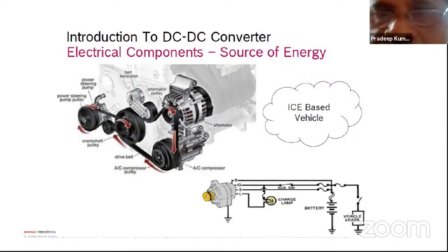Second is the technology associated with this. Endurance: how long it will last, what will happen to the battery life, what is happening to the battery while driving, how fast it is deteriorating, and so many things. And the last one and most important, safety. As I already mentioned, with a lithium-ion battery with a BMS system, you don't have to worry about safety as long as every parameter, current, voltage, temperature, everything is well maintained. So there is no problem. But the cost is the biggest problem as of now.